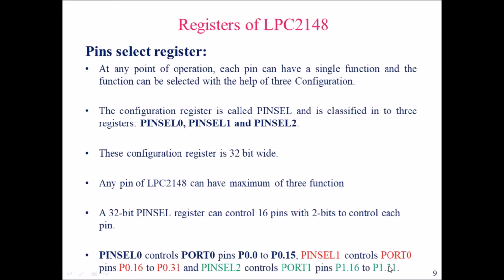As I told earlier, we cannot make use of the P1.0 pin to P1.15 pin. So those 16 pins cannot be used as general purpose input output pins in port 1. We can make use of port 1.16th pin to port 1.31st pin. We can make use of these 16 pins.